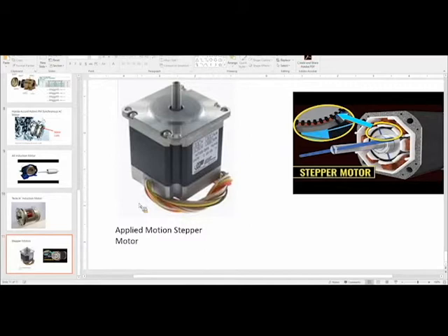If you de-energize coil A and energize B, it becomes clear that the rotor will rotate as shown. Okay, so just to note, in terms of function here, this actually behaves much more like the moving iron transducers or solenoids than all the other motors that we've seen before. It's looking to minimize the reluctance of this air gap here. So if we go back a step, when this coil was energized, this is the way in which we minimize the air gap.